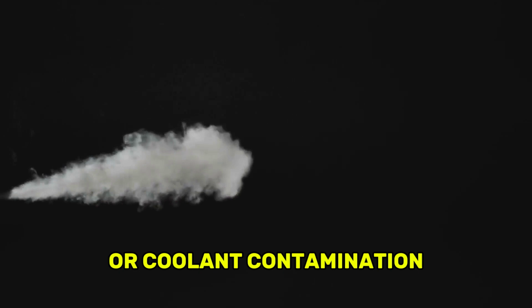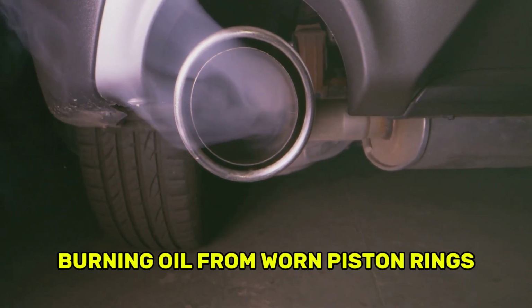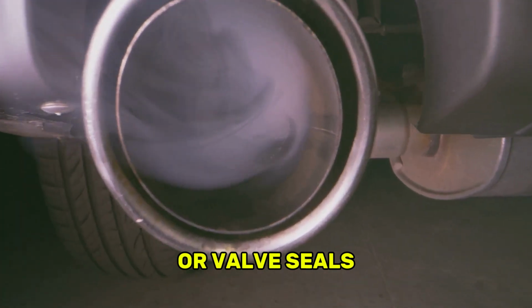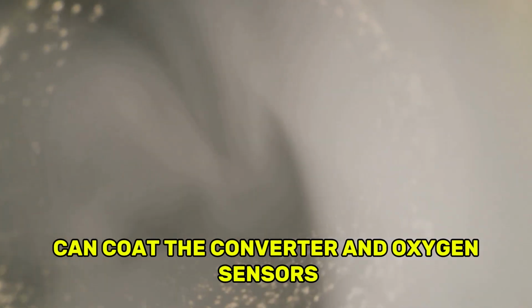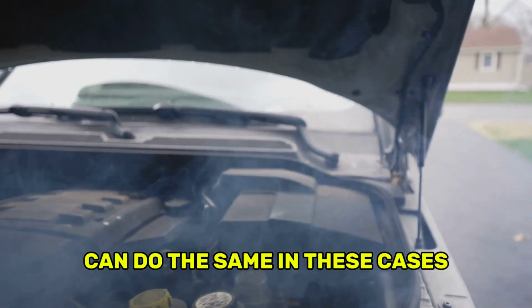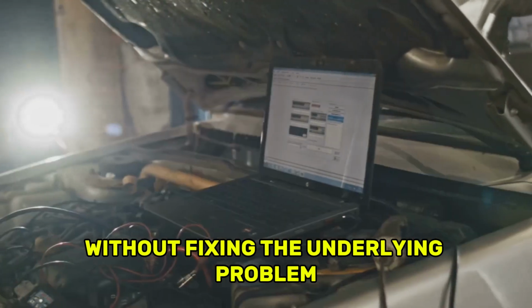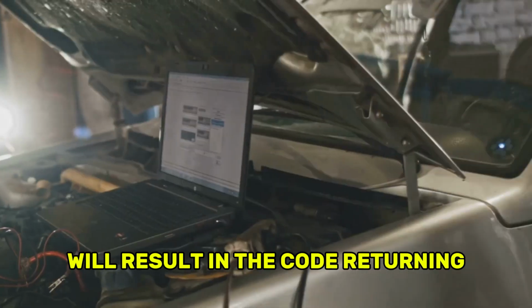Oil or coolant contamination can also reduce catalytic converter efficiency. Burning oil from worn piston rings or valve seals can coat the converter and oxygen sensors. Coolant entering the combustion chamber due to a head gasket issue can do the same. In these cases, replacing the catalytic converter without fixing the underlying problem will result in the code returning.